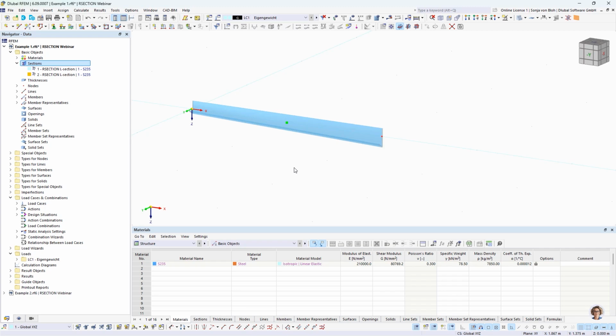The cross-section could only be interpolated if the cross-section change is displayed as a linear distribution. This is the case here. Only in this case, a design in the design add-ons is possible. It is important to note that the angle difference between the cross-section parts must not be greater than 0.1 radians. This means 5.7 degrees for both R-section cross-sections and database cross-sections.